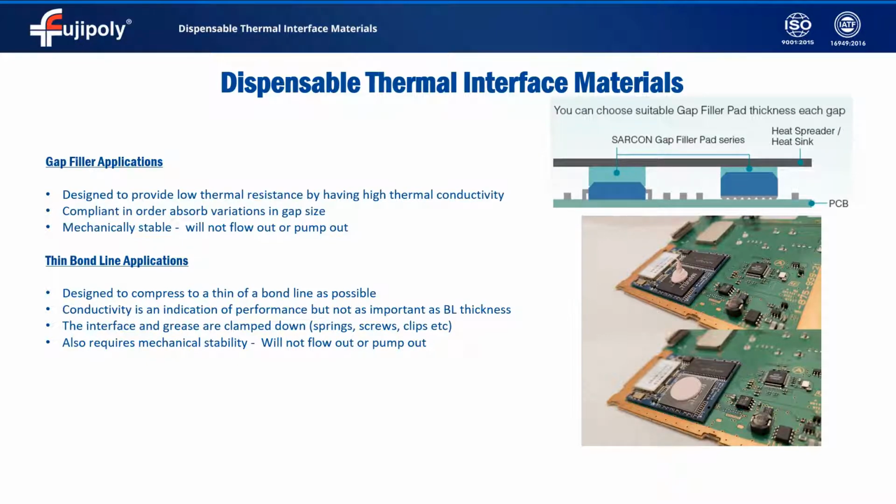The maximum gaps for dispensable materials will vary depending on their viscosities, how sticky they are, whether it's a vertical or a horizontal orientation, and whether they vulcanize or if they will remain in gel form. We always recommend thoroughly testing the stability of the material in each given application because everybody has different circumstances and the material might behave differently from one application to another.